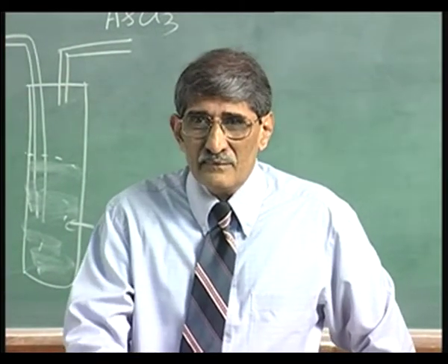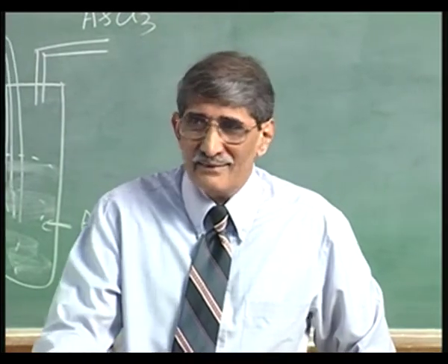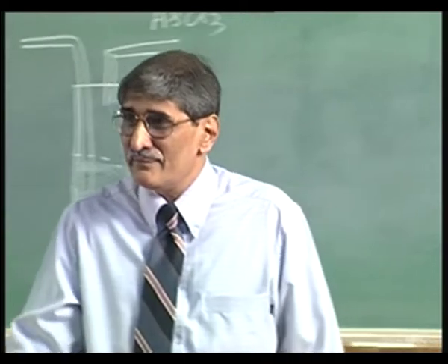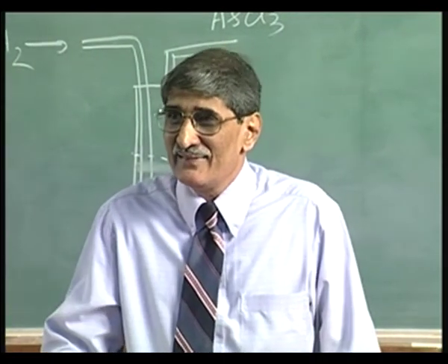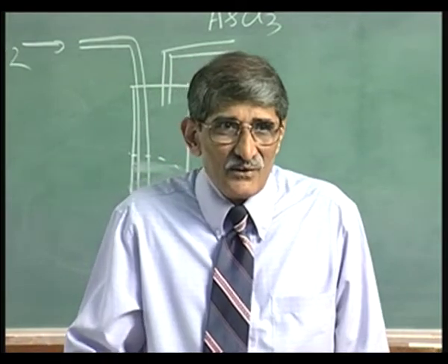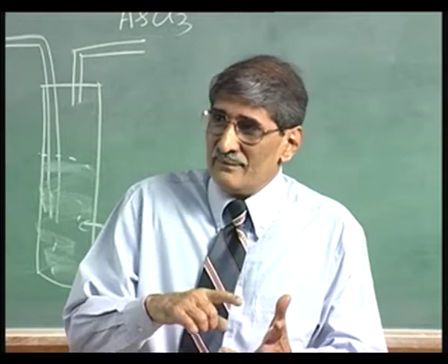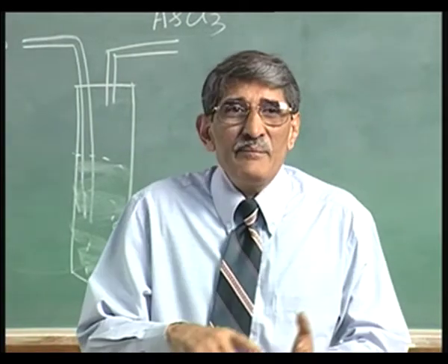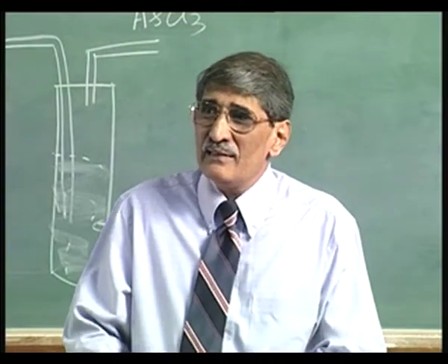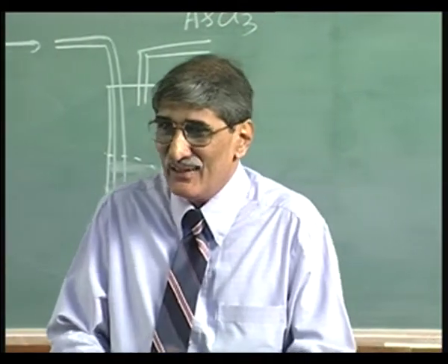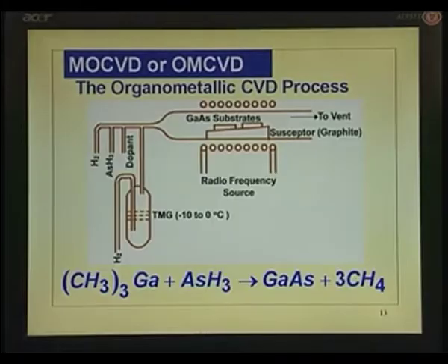Trimethyl gallium, trimethyl aluminum, you can tell names, trimethyl indium if you want indium, trimethyl zinc if you want zinc, dope it with p type, put another bubbler. So, either you can call trimethyl zinc TMZ or diethyl zinc DEZ, whatever names you want. Those are some of the things.